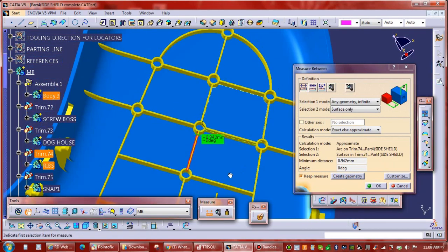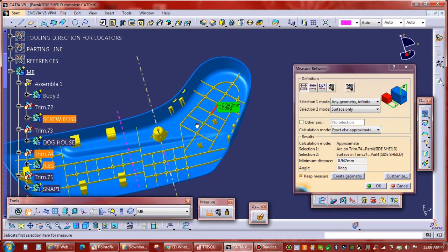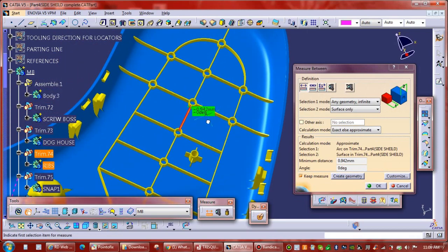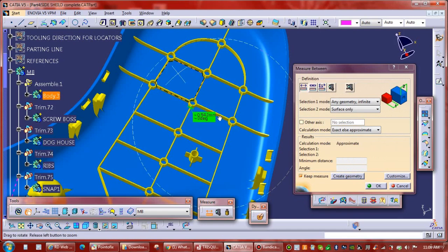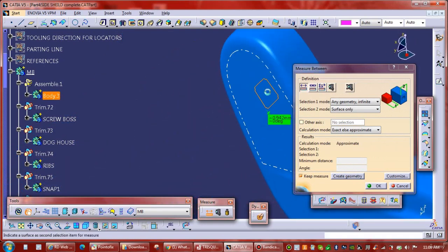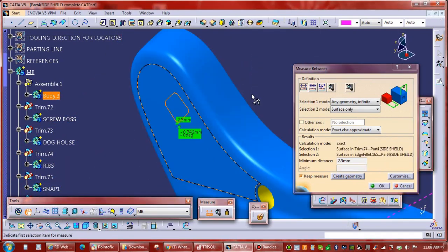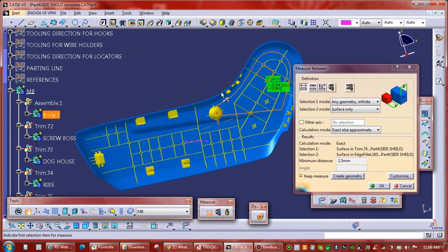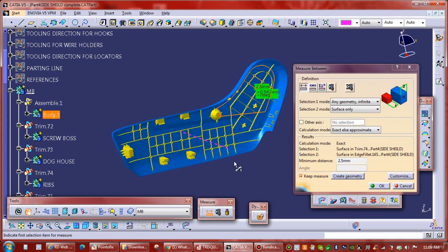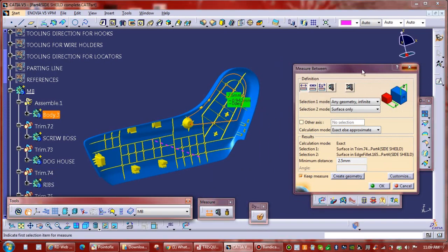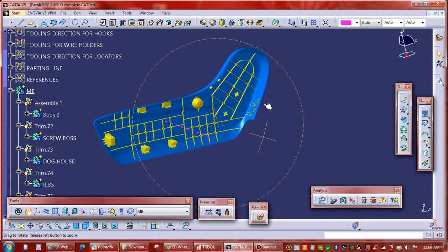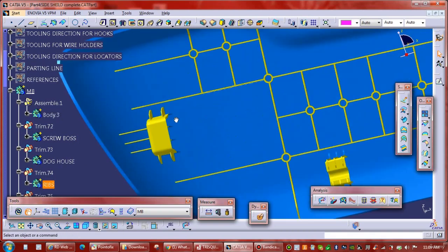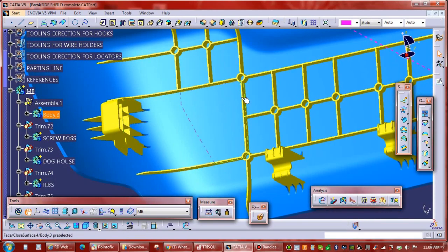The root thickness is coming to 40% for the plastic part, because my part thickness is 2.5 mm, as you can see. If we are using PP material here, then you should know how much root thickness you have to take. So these ribs are providing the strength.